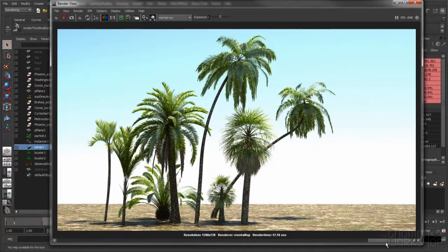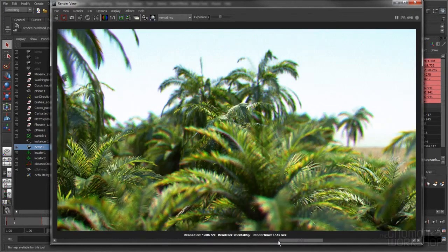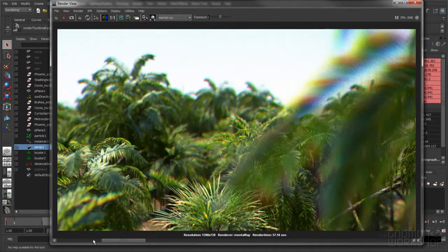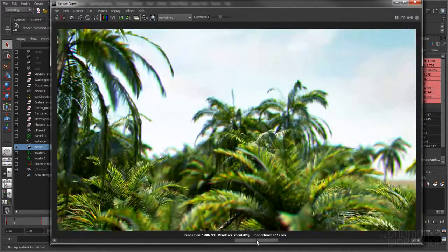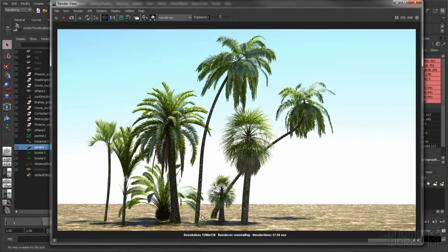So yeah, that's pretty much all I have to say about palm trees, really. Use Onyx because it's cool and it creates amazing palm trees. And as you've seen, like we did with this beach palm, it's so easy to just adjust the parameters to get a little different amount of bend in it, or change the spacing of your leaves, spacing of the stems, and so forth.